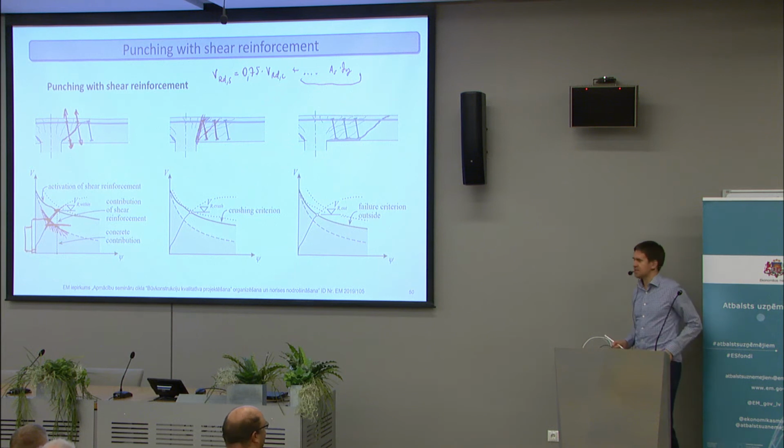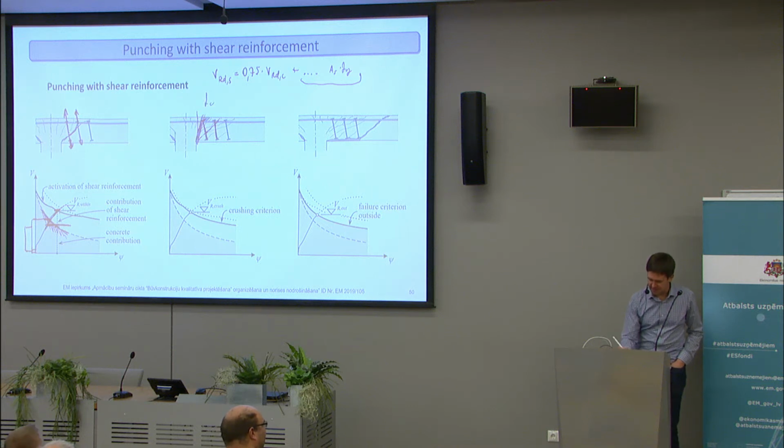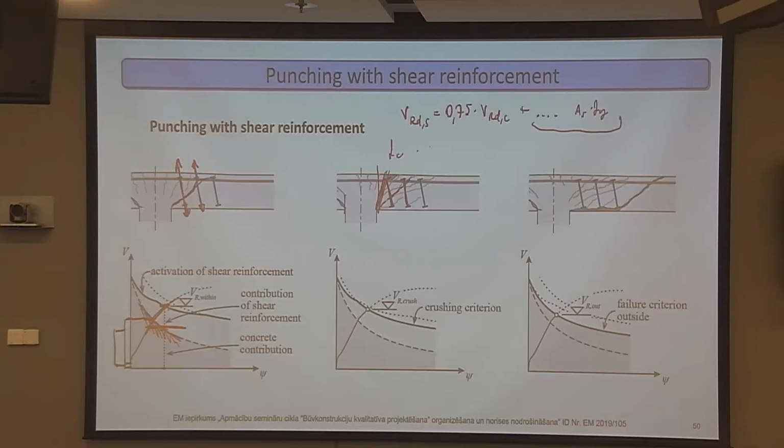Now in Eurocode, at first it was assumed that this should depend on fc, the concrete strength, and the perimeter of the column, u. Basically 4 times b_c, if b_c is the column side length. So in Eurocode, there is a formula to check the punching at the edge of the column.